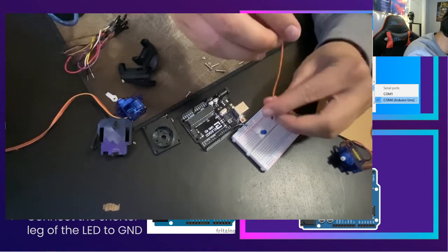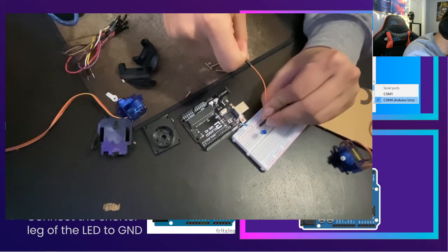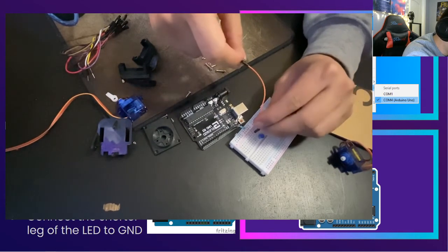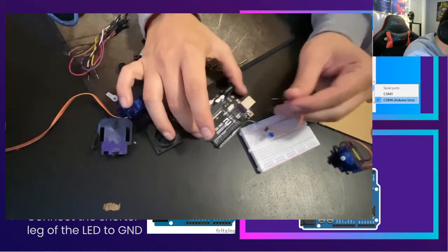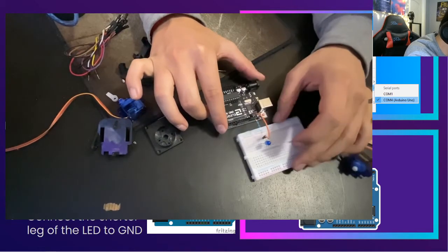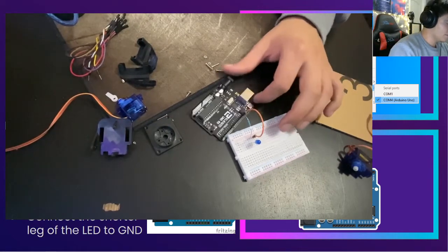We're gonna connect the other end. So these right here go this way, so there's a metal plate all along these that allows you to connect different components. So in this case you would connect the LED to that wire, and then we would go back to ground. The ground is right next to the pin 13, as you can see in the presentation as well. So there we go, we have it connected.